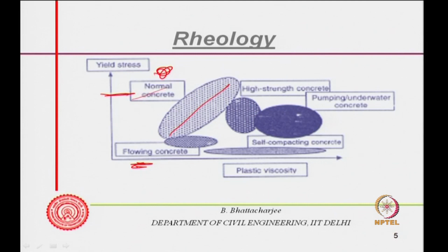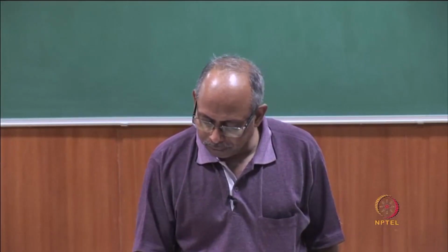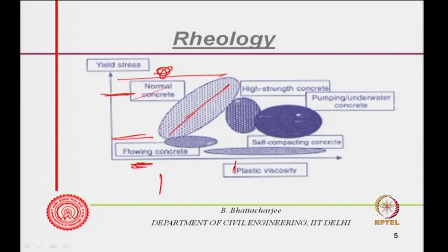High strength concrete, remember, has more paste, and therefore the yield shear stress might be somewhere there, depending upon of course their flow properties, and viscosity ranges varying from this to this. So, this is high strength concrete because their paste content is more. Pumping concrete should have low viscosity and low yield shear stress, and viscosity should be somewhere there, right.